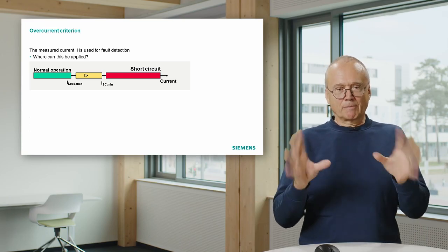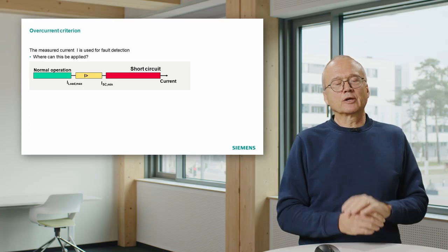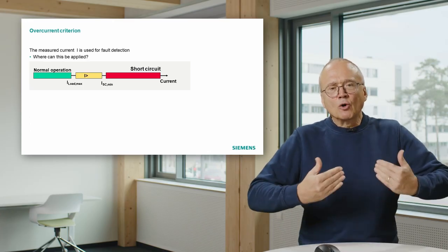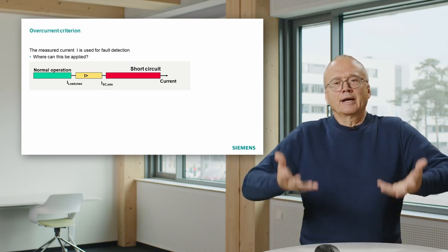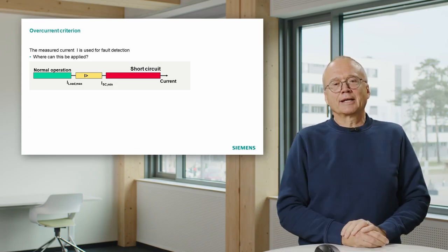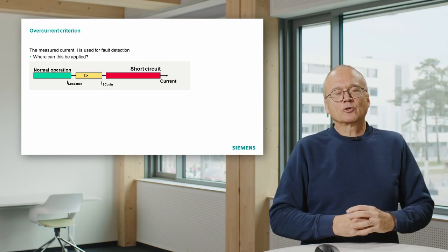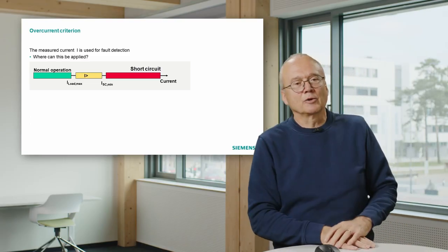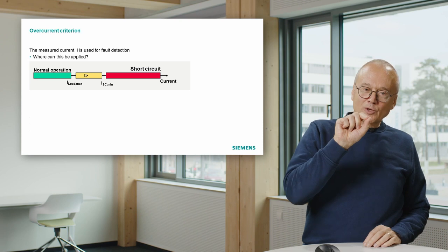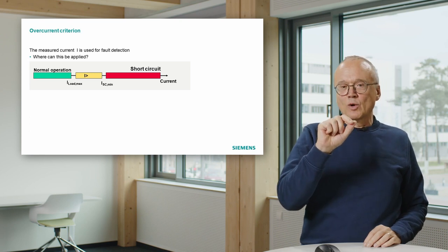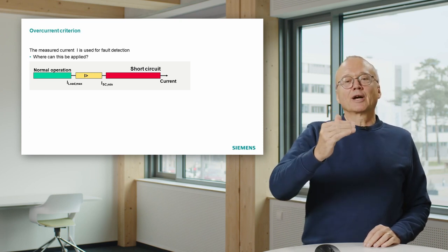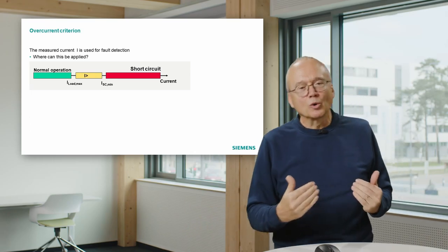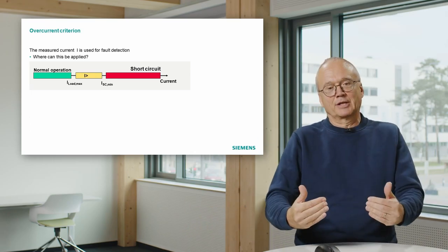You are happy, your repair work is done, you reconnect power, and then at the moment you reconnect power, all the air cons start running at the same time, and you get really a high current in the beginning, which slows then down a bit. But if now your setting is too low, with this high current you come above your setting and you will trip again. That means you won't get that system into operation again.